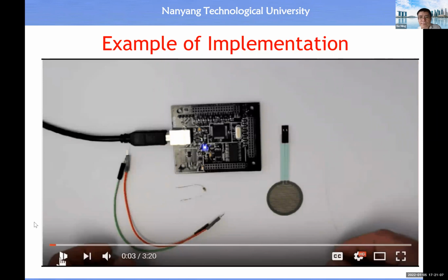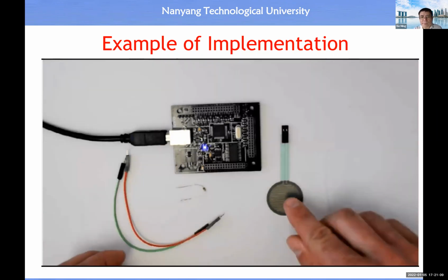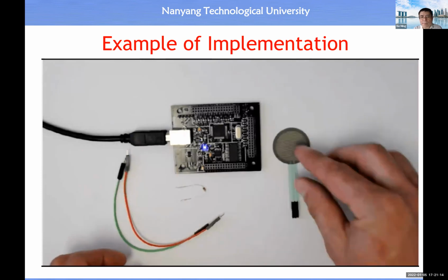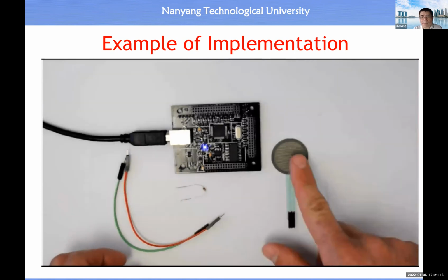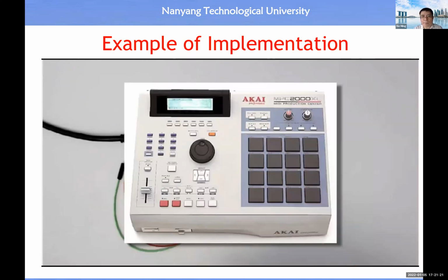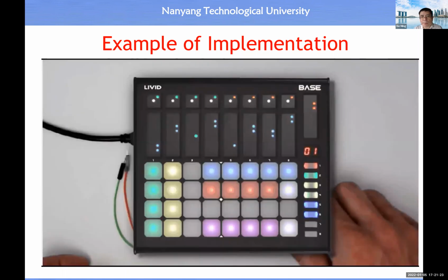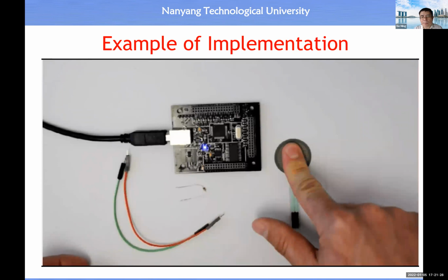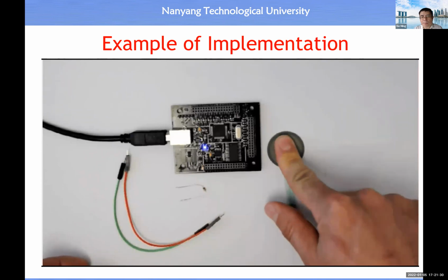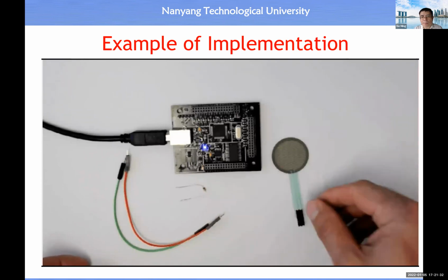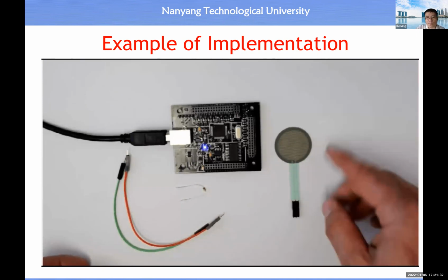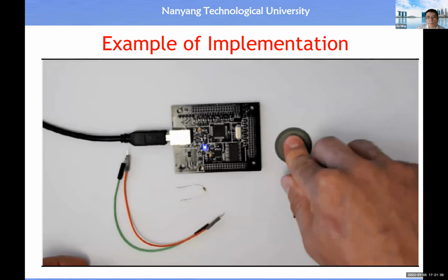So I'm going to show you how to connect an FSR to the Brain Junior. An FSR is a force sensing resistor, and it works like a button and like an analog control at the same time. So this is something that you'd see in a drum controller or a bass controller, anything that has velocity sensitive pads. The harder you press, the more velocity, and when you let go, the velocity goes down. So it acts like an analog control. In essence, it goes from 0 to 127, but instead of moving a controller, you're just pressing, and it's registering your force.